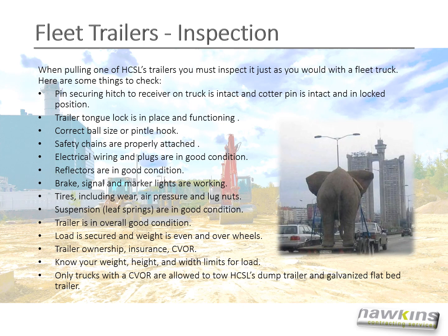Take a look at the trailer, is it in overall good condition? Make sure your load is secured and weight is evenly over the wheels. Check for the trailer ownership, insurance, and CVOR. Know your weight, height, and width limits for the load. Only trucks with the CVOR are allowed to tow Hawkins dump trailer and galvanized flatbed trailer.